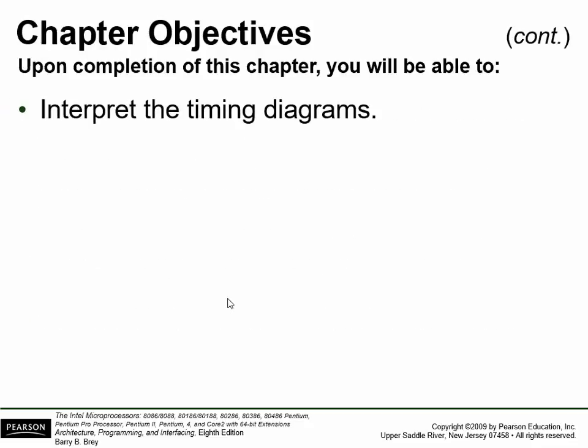Timing diagrams, we'll go through some of those. Those are the bread and butter of any digital engineer. And when I include digital engineers, I include embedded processors, microcontrollers, microprocessors, and advanced digital logic such as field programmable gate arrays. Everyone had basic digital, correct? Well, in advanced digital, you go into custom logic, where you design circuits using Verilog or VHDL. Again, timing diagrams is how you troubleshoot and debug those things.